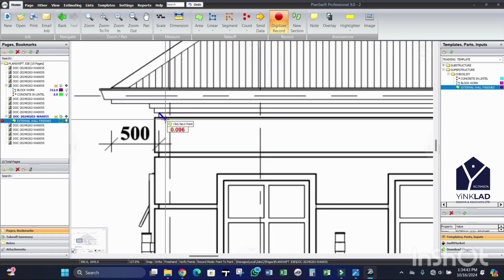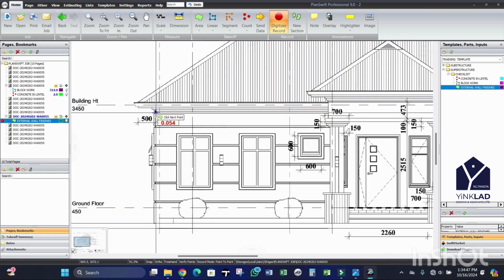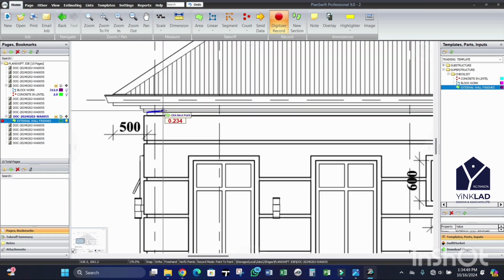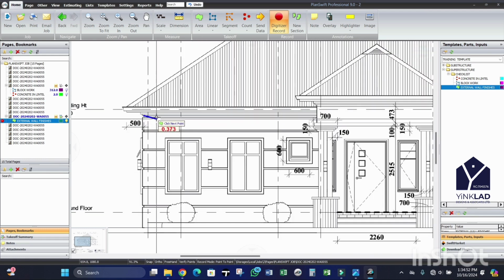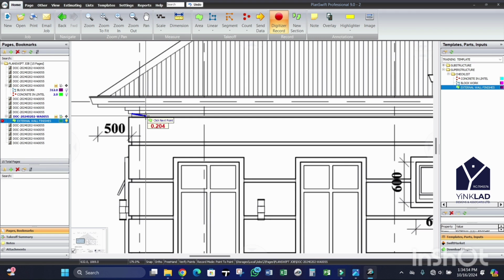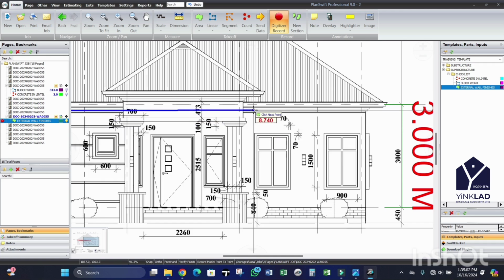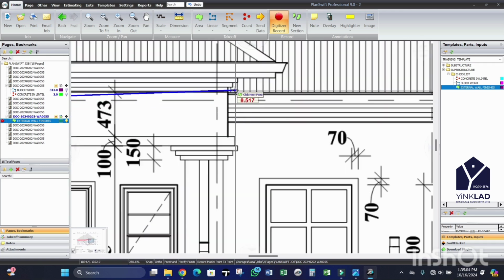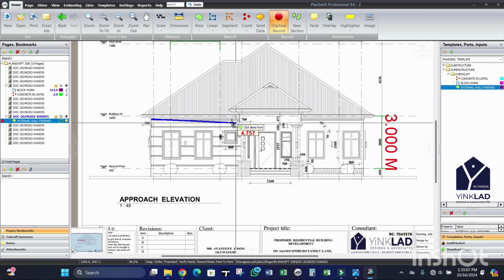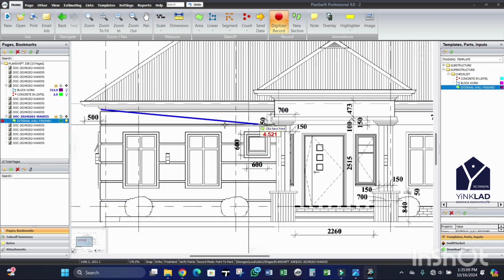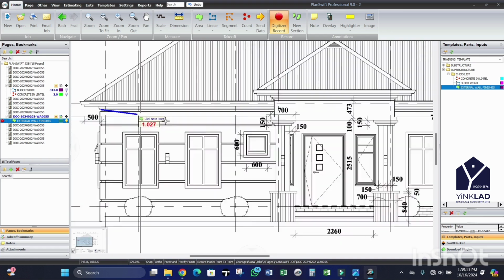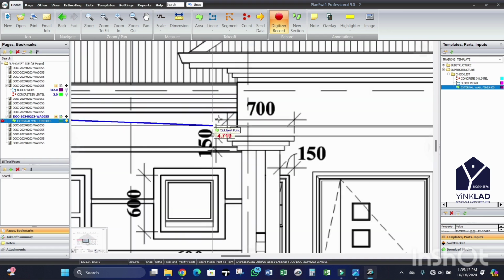Because this is a parapet, sometimes you don't plaster it. If you use marine board, what I'm going to do is just to screed it and paint it. Sometimes the parapet can be plastered, sometimes it cannot. So just assume that you don't want to plaster it. You understand?